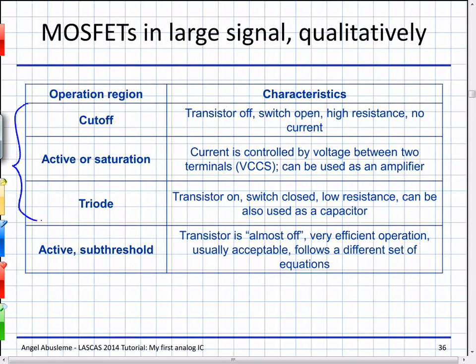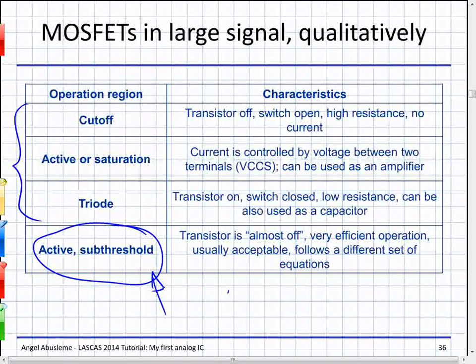Yeah, so this is the most common. This is what we usually teach in a basic electronics course. But this is a very important region because here you have a lot of power efficiency. And even though the performance is not that good, for very fast transistors you can make a very fast, very low power circuit in sub-threshold.